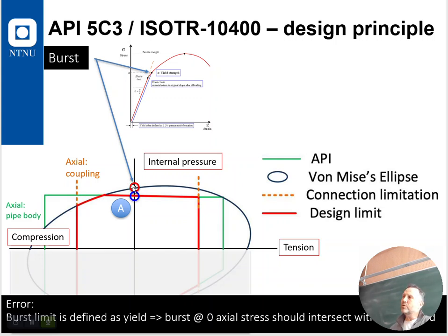Yeah, and zero actual stress would mean where this axis crosses the von Mises, right? Because in that point there's no actual stress, so they should fall together, and the difference would be the 0.875, the wall thickness correction.